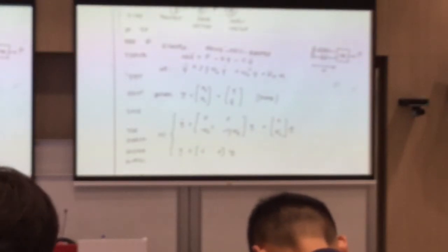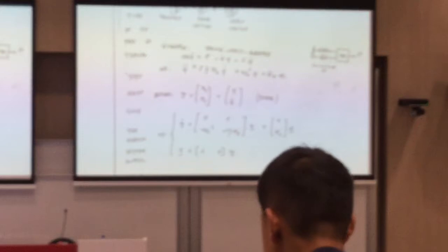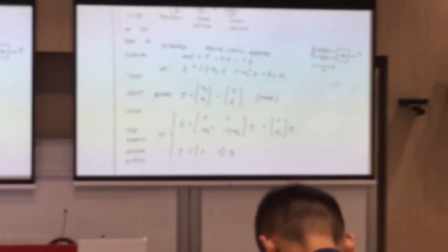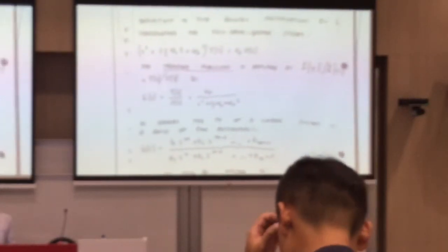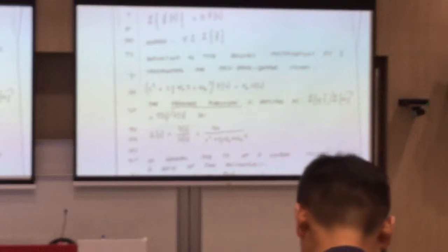Basically, no matter whether you talk about the state space or the Laplace, they just want to simplify your differential equation. They want to lower the order of your differential equation. For the Laplace, through the Laplace transform, you convert your high order differential equation to a high order polynomial function. Then after you solve the polynomial function, you are able to use the inverse Laplace. So no matter whether you talk about the state space or the Laplace transform, they are mathematical tools for you to understand the characteristics of your differential equations.